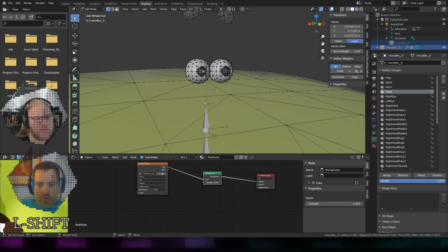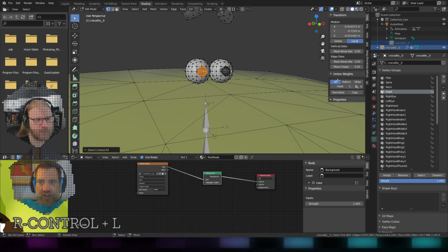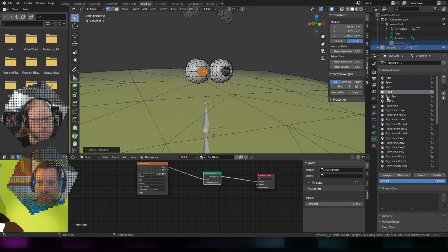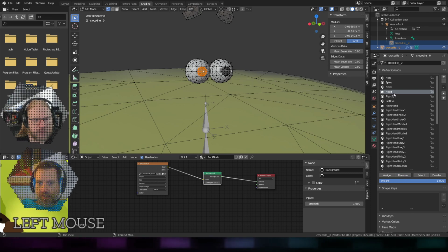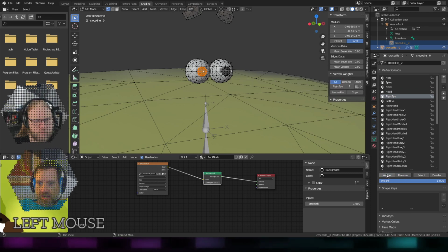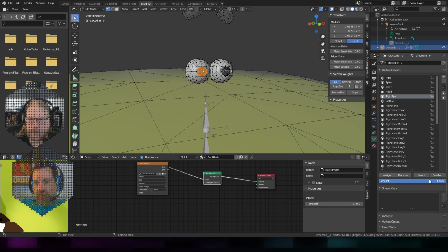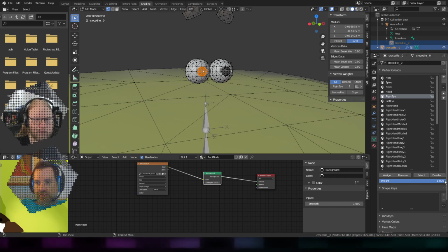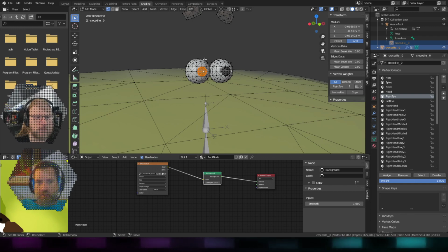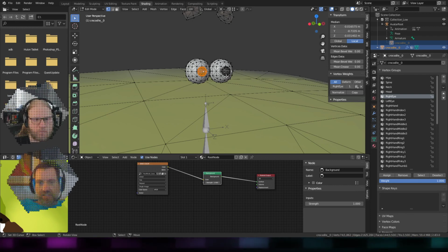But I'm gonna select the one pupil, and this is his right eye. So I'm gonna select, let's remove it from head and assign it to right eye. And by the way, when you assign, it's based on this weight underneath. This is a slider. So it's 100% or 1 all the way to that bone. And that's how you do gradual.